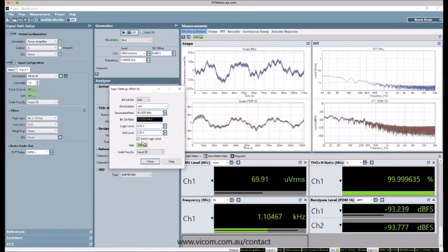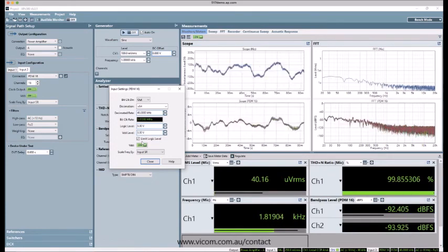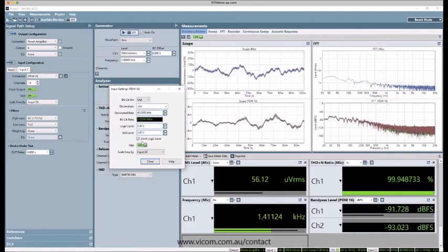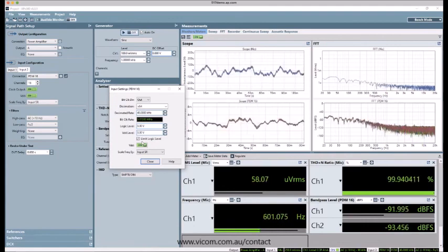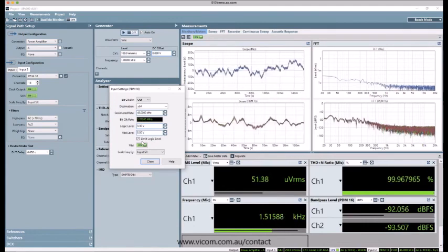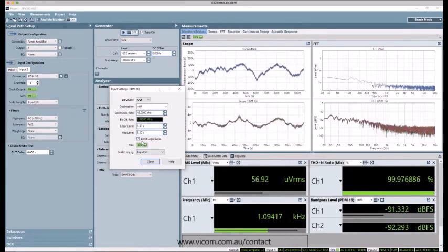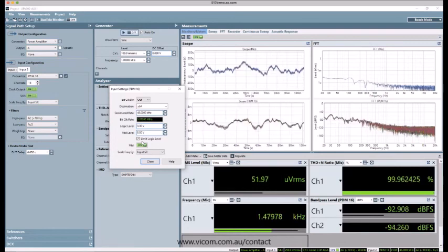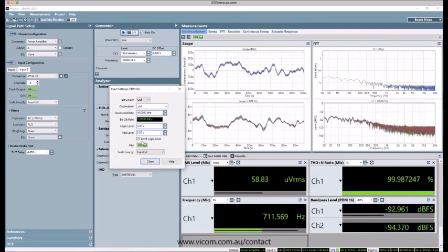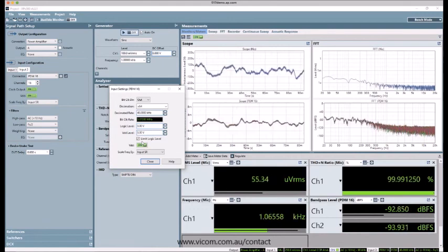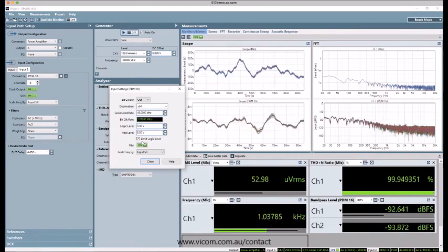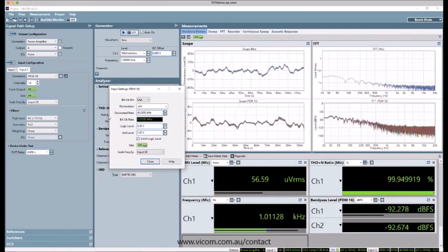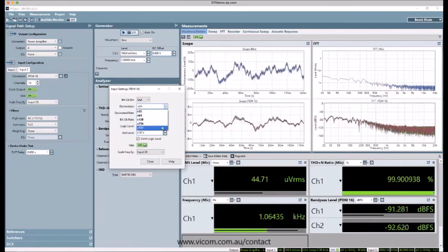I won't go into the whole explanation, but the quick and dirty of it is that it's a 1-bit A to D converter, as bizarre as that might sound. And it comes out at a pretty high rate. In my current configuration, it's coming out at 3 megahertz. And we then decimate or low pass filter that to demodulate the baseband audio. And the question is, at what rate should you do that?